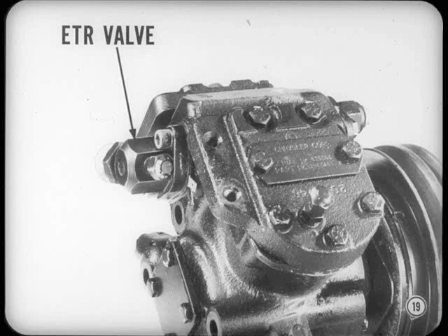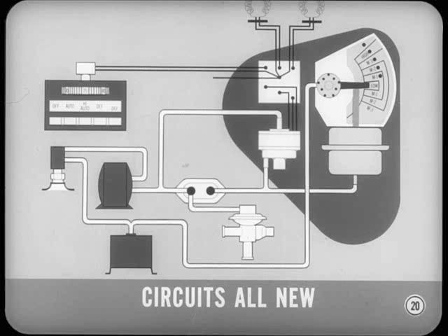The refrigeration section of Auto-Temp is almost identical with the conventional unit also. The only real difference is the substitution of the evaporator temperature regulator valve for the evaporator pressure regulator valve. But they have the same general function, so basic refrigeration diagnosis won't be changed. The control circuits, both electrical and vacuum, are entirely new and include some components that we haven't seen before. So our diagnosis discussion for today will concentrate on the controls.